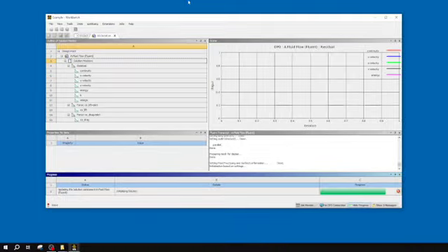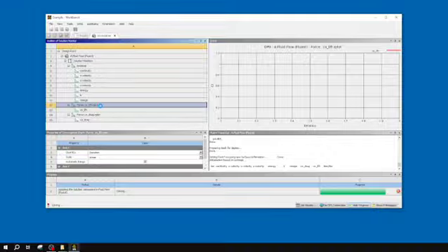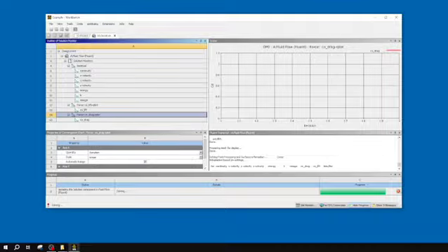So we have a bunch of things that we can now look at. To start, you'll see that it expands out this branch with two different plots. One is my residuals, and one is my coefficient of lift and coefficient of drag plots. If I click on the different ones, you'll see this update. It hasn't done much calculating, so there's not much to see currently.